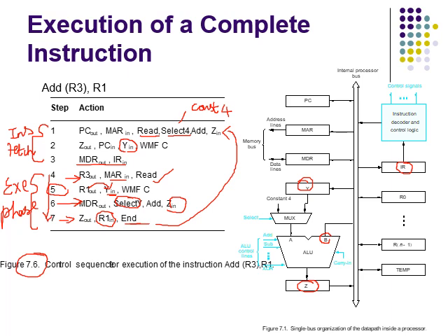To speed up the execution of the branch instruction, this value is copied to register Y in step 2. Since step 2 is a part of the fetch phase, the same action is performed for all instructions. This does not cause any harm because register Y is not used for any other purpose at that time.